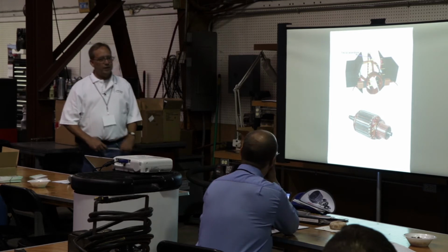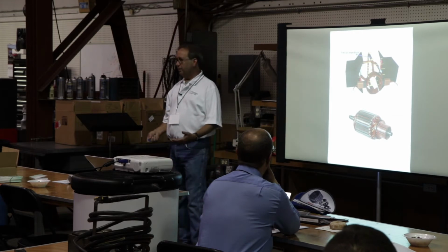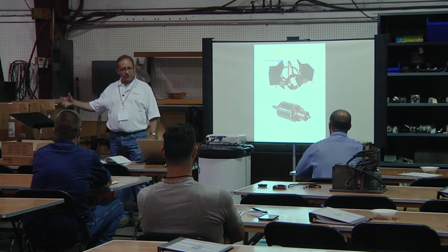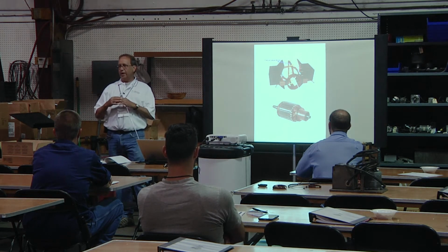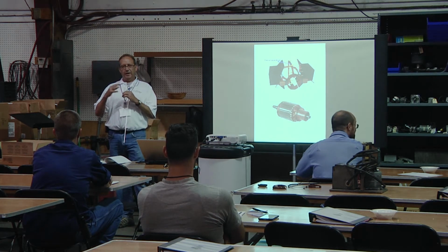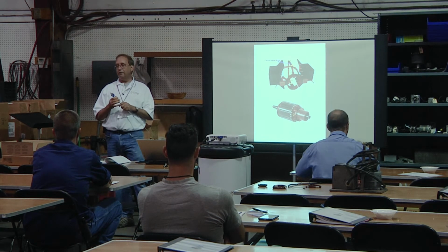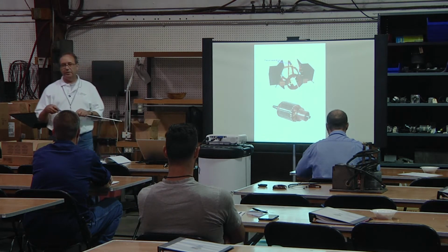The reason for that is that your back EMF, that voltage that you're generating in the coils that are right over the top of the brushes, is meeting the voltage going in. So you have them meeting at the same junction, and it creates a spark. Sometimes a pretty good ring of fire too. Depends how far off it is and how high that potential is in that back EMF.